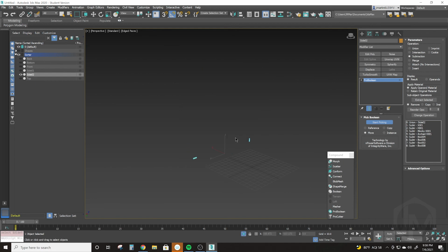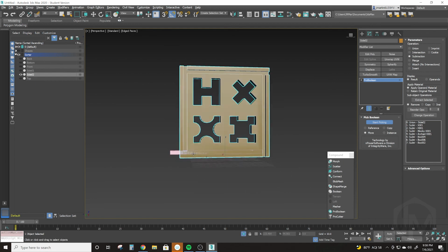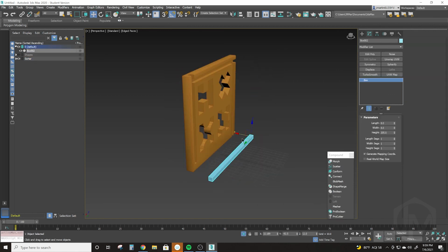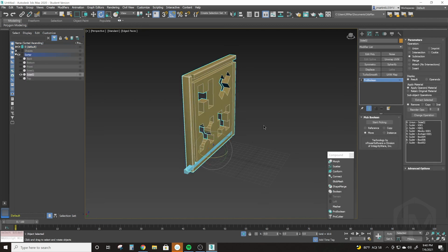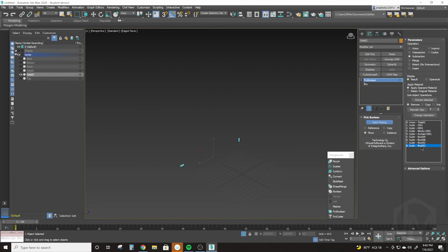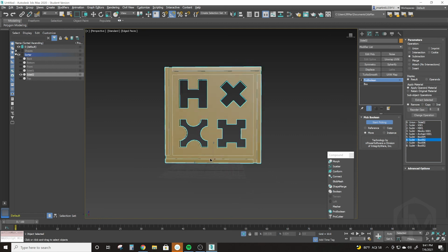Here, I run into a problem. It seems that subtracting the volume of the last detail box causes the rest of the object to disappear. After double checking the transformation values for the detail box, I found that changing the operation order solves the problem. This is achieved by first selecting the desired operand from the list, then adjusting the number value in the field next to the Reorder Ops button, and then clicking the Reorder Ops button to confirm.